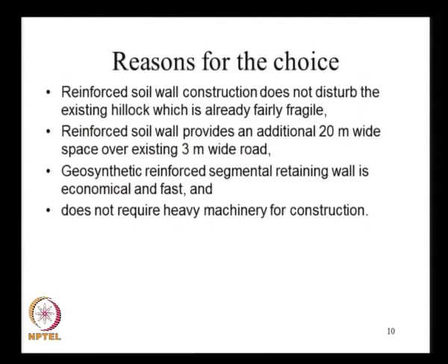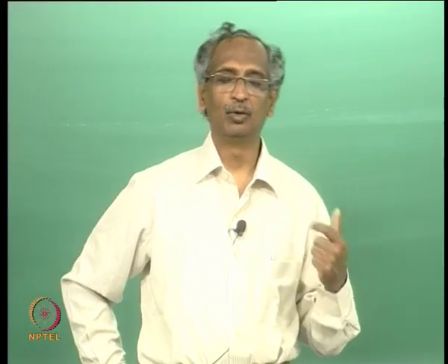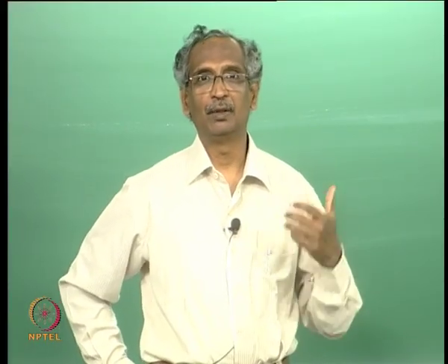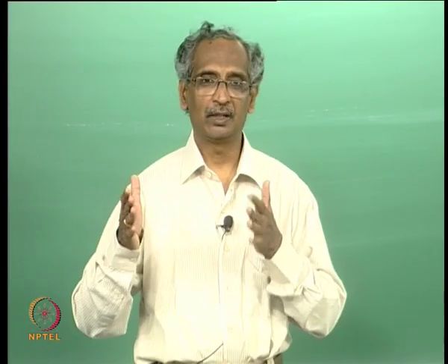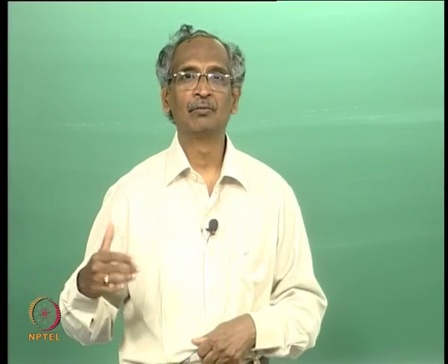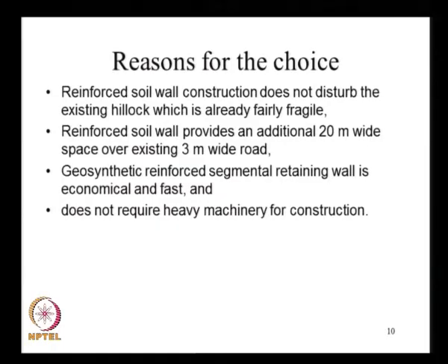So, the reasons for the choice of the reinforced soil option: the construction of the reinforced soil wall does not disturb the existing hillock, which is already very fragile. The construction of the reinforced fill does not impose too much load, because we are only placing the soil, and our facing panels or facing elements are all very lightweight.